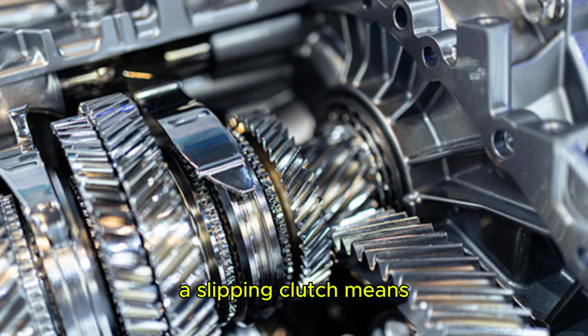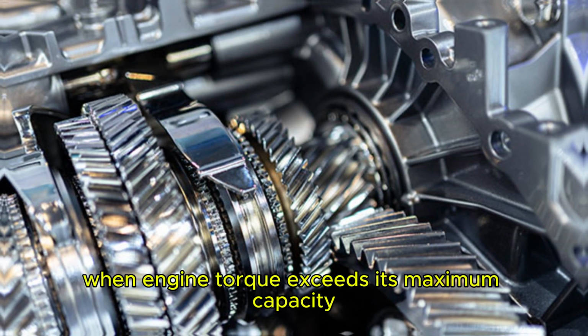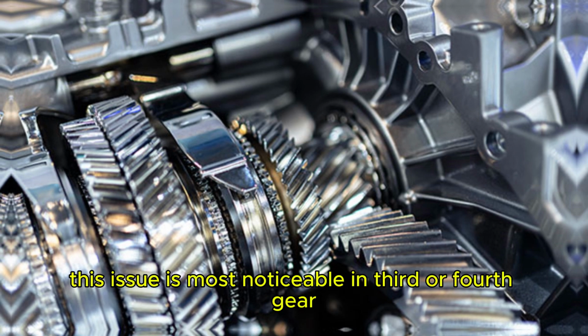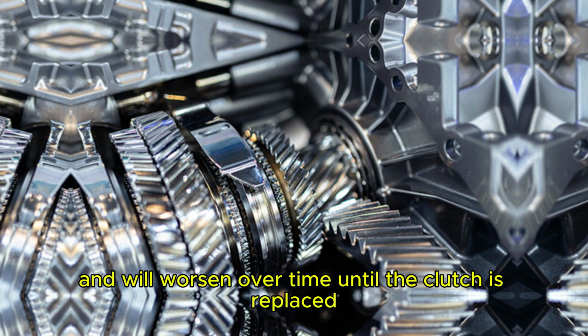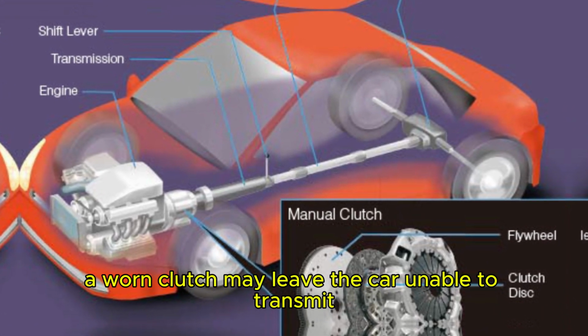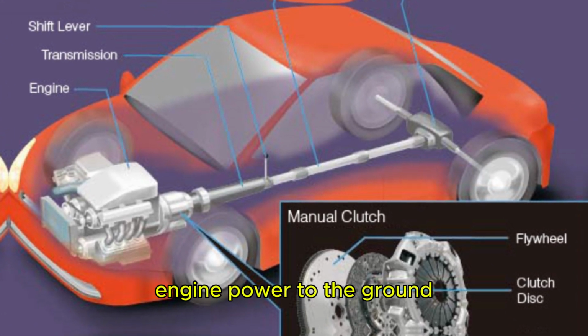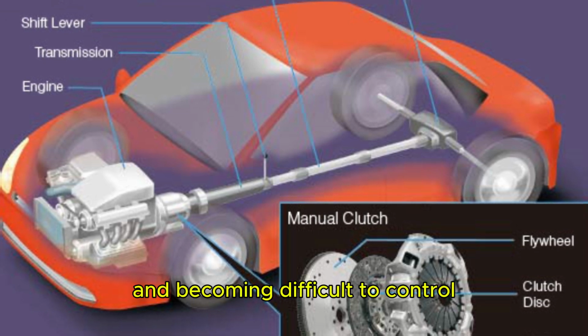A slipping clutch means it has lost the ability to hold the same amount of torque, causing intermittent sliding when engine torque exceeds its maximum capacity. This issue is most noticeable in third or fourth gear and will worsen over time until the clutch is replaced. In rare cases, a worn clutch may leave the car unable to transmit engine power to the ground, causing it to lose torque while accelerating and becoming difficult to control.